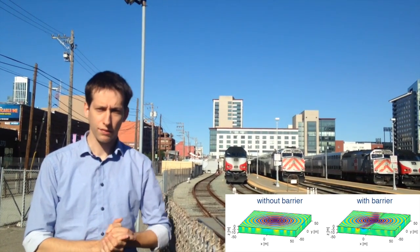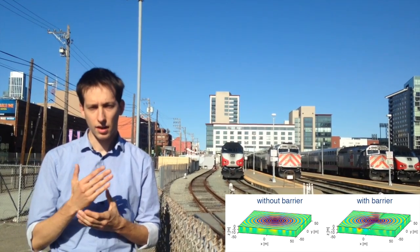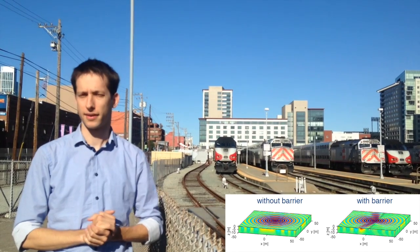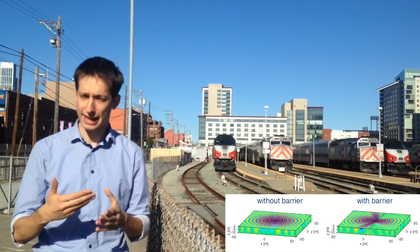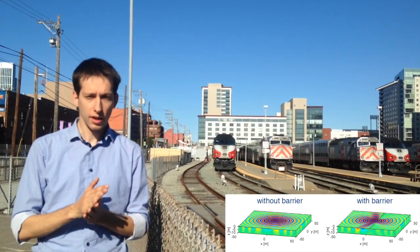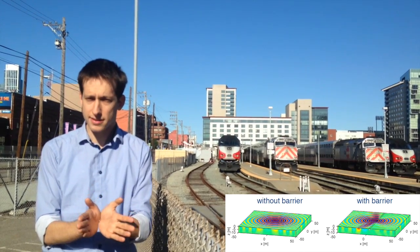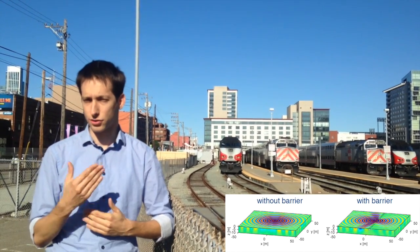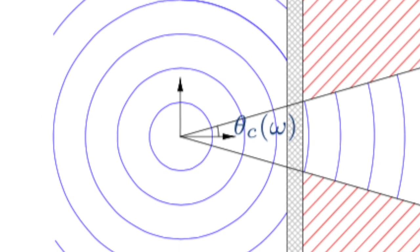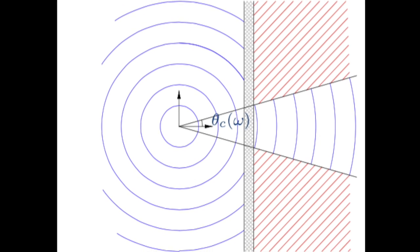This is mainly the case for waves that impinge at an oblique angle on the barrier. Waves impinging perpendicular on the barrier still propagate unhindered through it because the wavelength as observed by the barrier is still too large. This results in the existence of a critical angle behind the barrier, which delimits the area where vibration levels are strongly reduced. This fundamental insight into the behavior of stiff wave barriers allows formulating simple rules of thumb for the critical frequency and critical angle.